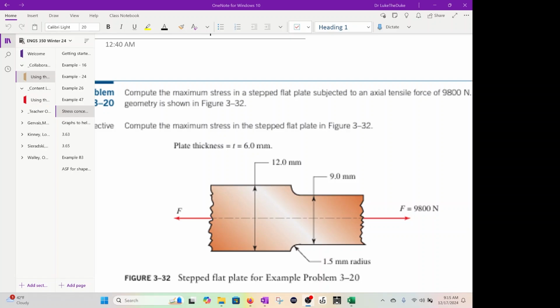Okay, in this video, we're going to look at stress concentrations, do a few examples, and then get into area shape factor and find a design factor. If we look right here, there are certain conditions where you have fillets that are going to create a stress concentration, a point where the stress is going to be higher. Depending on the situation, we can find those maximum stresses.